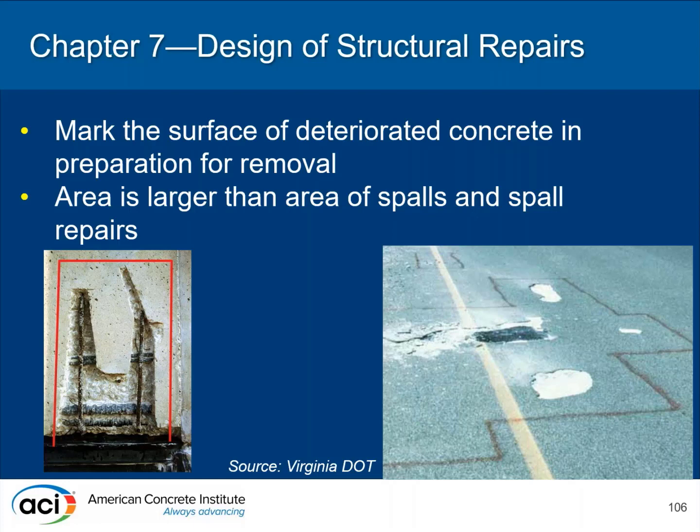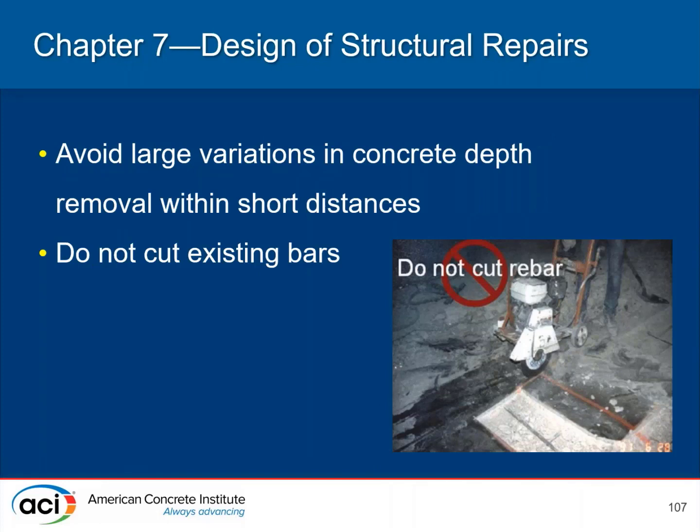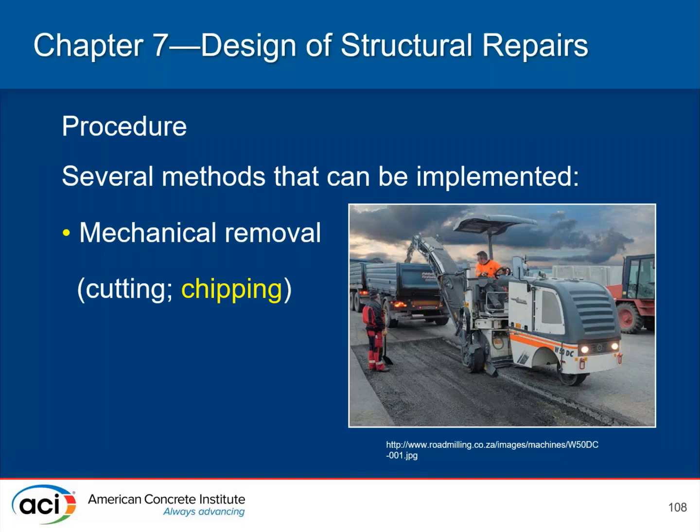And this is again just showing that removal of concrete in isolated places is not a good approach because of the stress concentrations that develop. So that repair area on the left would include removal in a simple geometry. The other thing that's a concern or critical is that large variations in depth aren't experienced, because again, creating stress concentrations, and again, not to cut existing reinforcing steel bars.